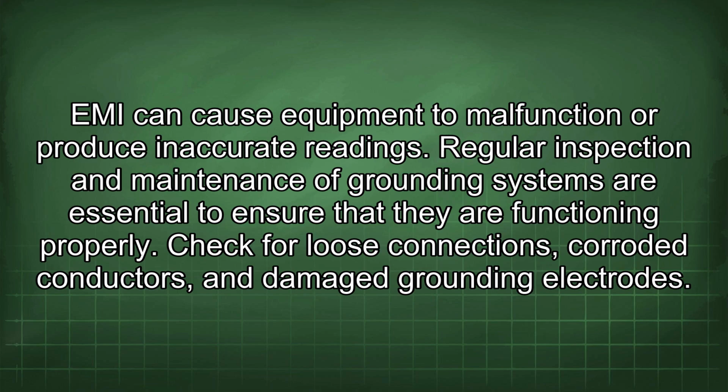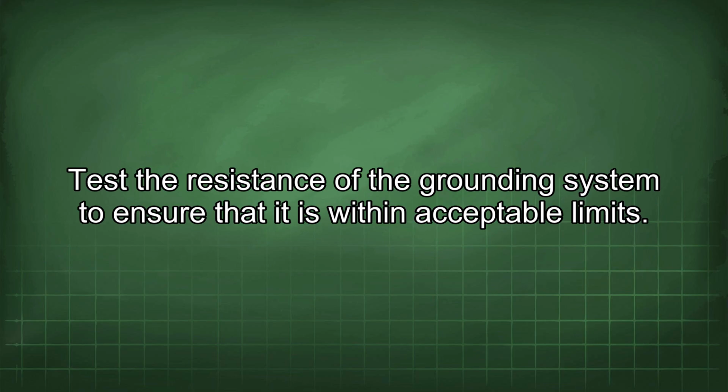Regular inspection and maintenance of grounding systems are essential to ensure that they are functioning properly. Check for loose connections, corroded conductors, and damaged grounding electrodes. Test the resistance of the grounding system to ensure that it is within acceptable limits.